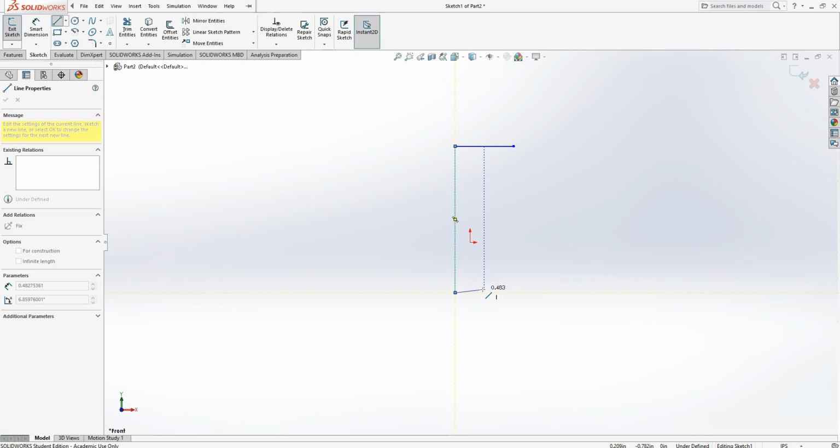Keep moving. Now, you will see these little hash marks populate. This is just indicating that there's a certain relationship there. Now, if I were to stop there and go up, I would be at the midpoint of the line segment I just created. I don't want that, but I do want you to notice it. So I'm just going to flatten this out, 90 degrees. You'll notice that there's a little degree indicator there. Reference the book, and you will know what all these little symbols mean.